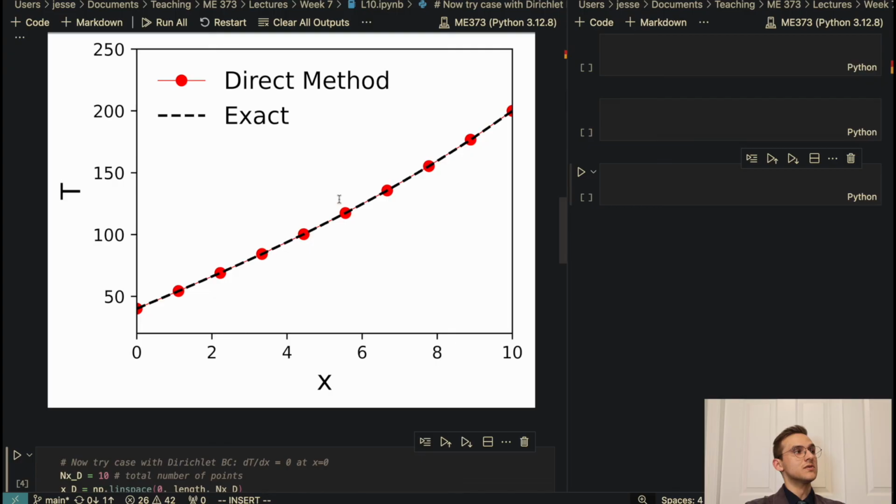You can also end up with system matrices that are ill-conditioned, meaning they're difficult to invert. Or in other words, the overall matrix vector equation that you're trying to solve is nearly singular. So the solution vector is very close to 0 for all entries. That can cause some issues as well. But we'll talk about those types of issues in the future.